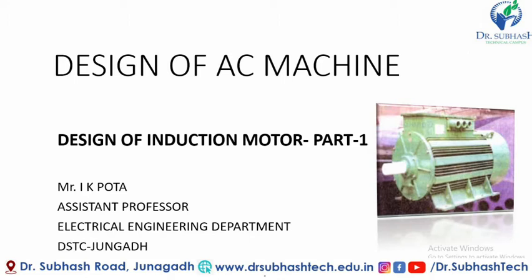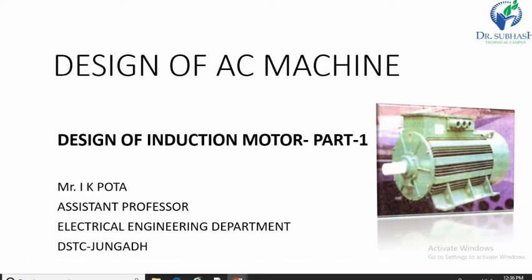First of all, what is design? A design is a systematic process of finding the dimensions like diameter, length and area, and some electrical parameters like resistance and reactance of a machine, which will satisfy the given specification such as the rating of machine, speed of machine, starting torque, allowable temperature rise and various service conditions.